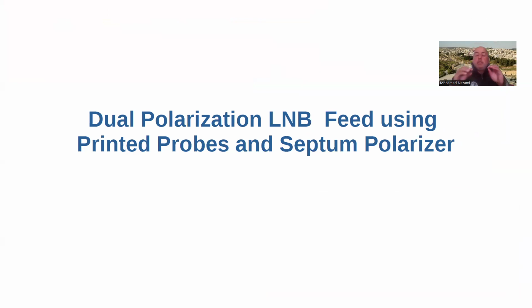Now remember, the septum polarizer is only a small piece that decomposes, or demultiplexes, if you like to call it, the E field from a circular polarized signal into both vertical and horizontal, or from an elliptical polarization into whichever directions you want.